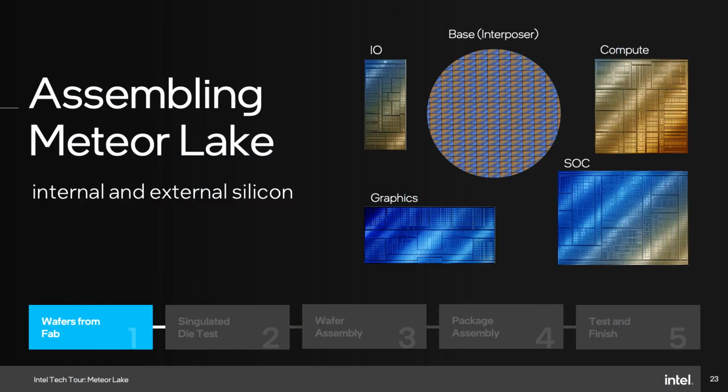So Foveros, if I understood correctly, you can correct me if I'm wrong, is we have this base wafer in which we have other tiles that come on top of it. So can you tell us a little bit more about that and how is it assembled? Sure, that's exactly right. We actually start with all of them in wafer form. We have a base wafer, and then we have all the top tiles come to us in wafers. Some from internal, like our compute die on Intel 4, and then the other die that come to us from external foundry. We bring them in. All the top die we take through what we call die prep or singulation. So we'll cut up the die, singulate the die, and then we'll send them to sort.